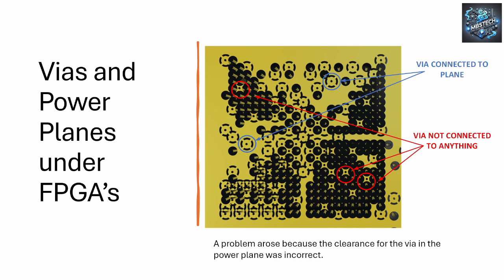Here's an example of what I'm talking about. Here's a picture of a bad set of clearances for a 484 BGA. It's got a 1mm pitch. This is an Igloo 2 example I've set up. The wires in blue that I've circled are ground wires. They are connected directly to the plane.